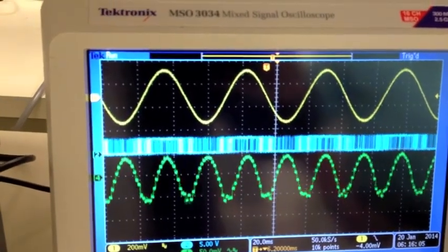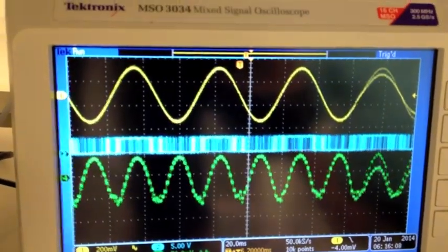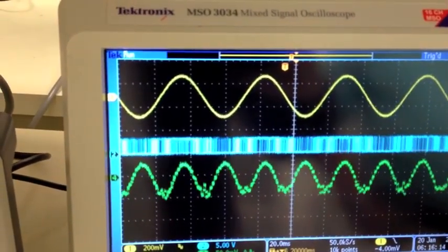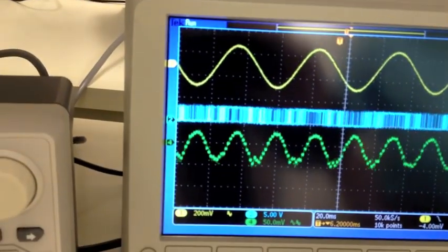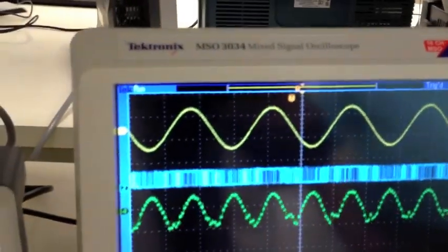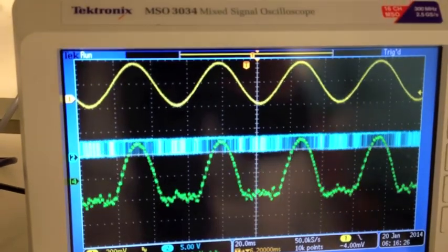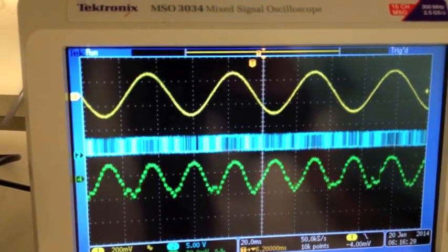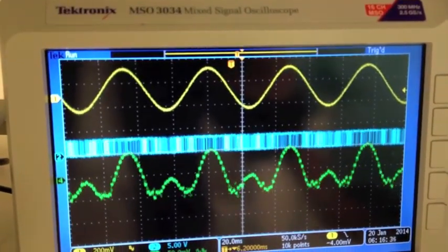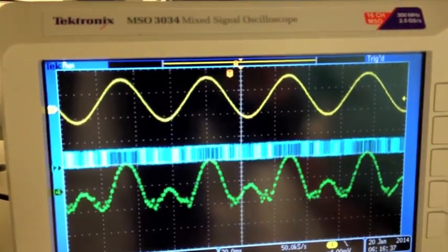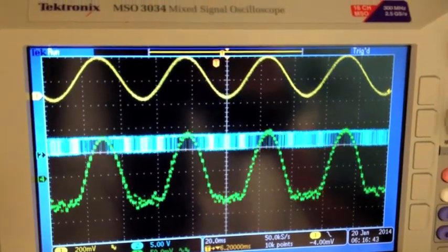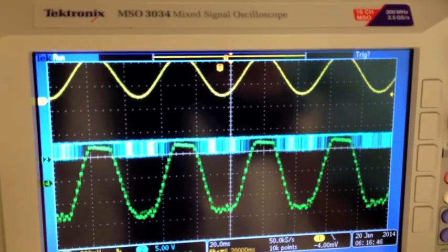The most interesting part is that we can demonstrate the offset. Theoretically, for a waveform rectified with offset, you're going to see uneven sine waves. Let me see what the offset is. Okay, now let's start with offset. Oh, it's too much. Keep increasing it. So you can see some parts are getting larger and some parts are getting smaller, until we can see the whole sine waveform. Oh, the peak is saturated.